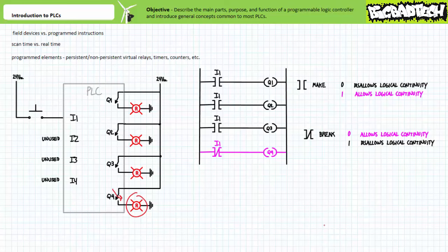Scan time is a sequential reading of a PLC program from top to bottom and then returning to the top. This means if a CPU is currently scanning line 4 and something on line 1 changes, the CPU needs to read through the whole program before it starts at rung 1 again to notice something has changed.